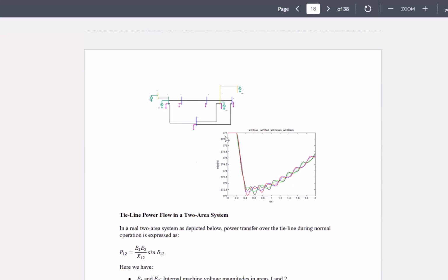Okay, and then because of these changes, there would be some oscillations in frequency. So, for example, in here, see that if there is a change in the frequency, then this omega, which is 377, which is 2 pi f, because of that change in the load, goes to a lesser value, and then the frequency of the system tries to go back to the same 377, but it takes a while.